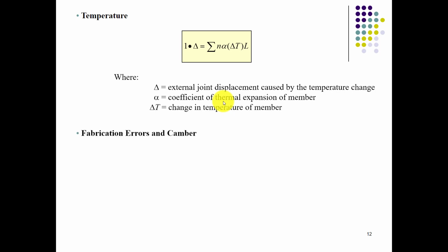So for the fabrication error, for example, you have made your steel elements, but there is some deformation, or some settlement upon the support, and due to this settlement, the stresses are being transformed into some internal forces like compression and tension. Then you can calculate the amount of deflection by that fabrication error by means of this formula.